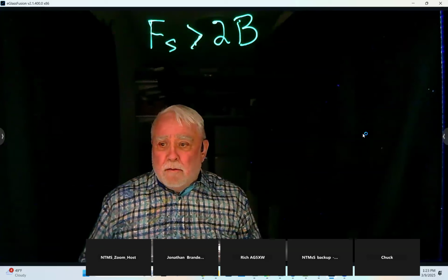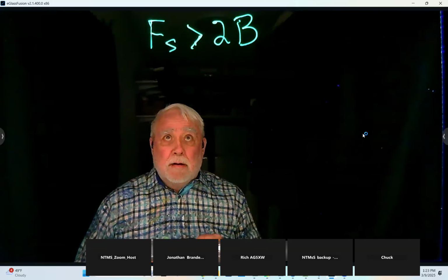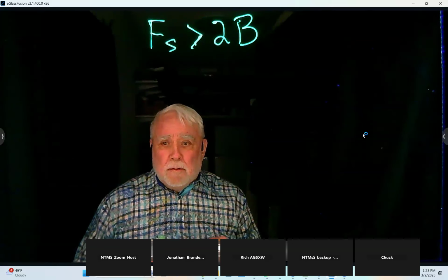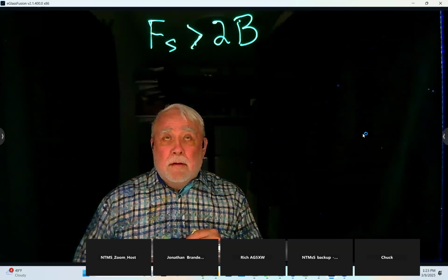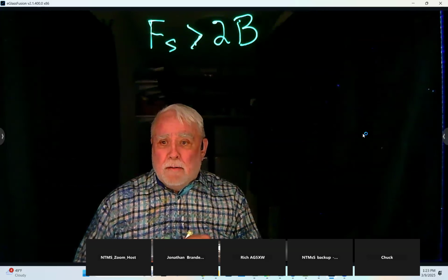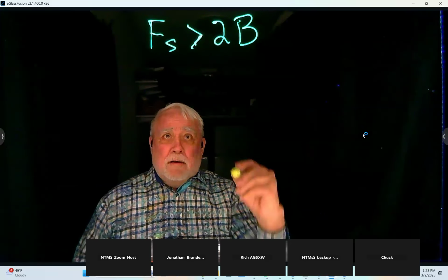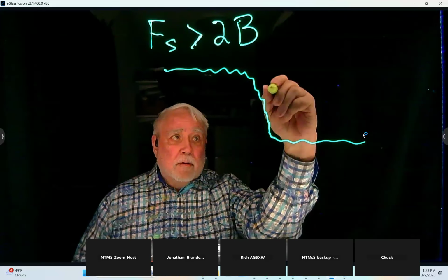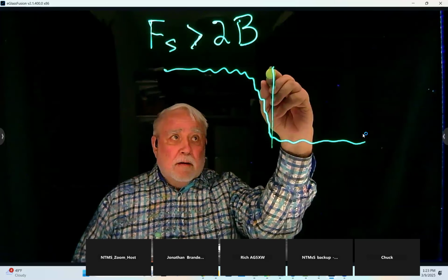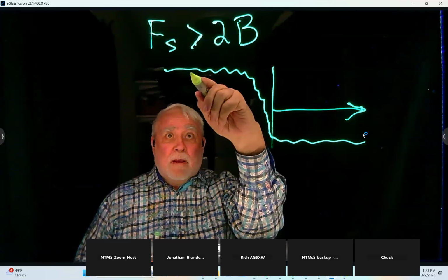Our SDR radios, like your Pluto and your RTL SDR, are designed to filter frequencies just above the 2x sample rate before it's sampled. So in other words, it's looking at the frequency here and it sees it drop off and there's the noise level. It starts off by filtering that before it tries to sample.